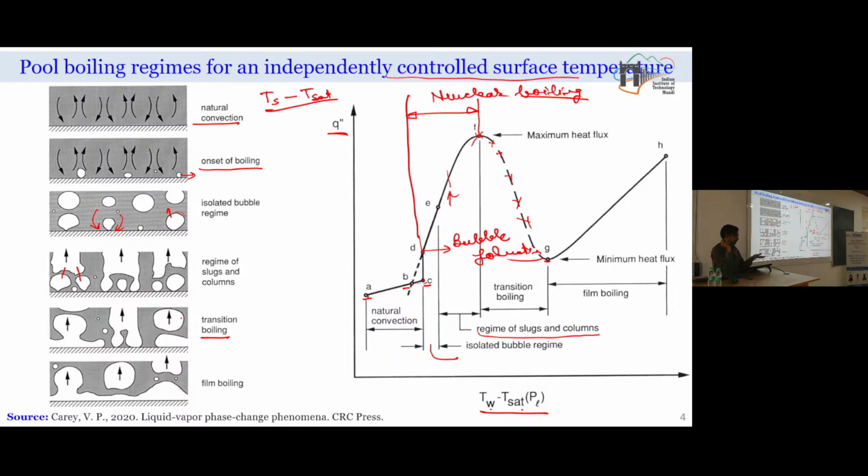of bubbles are forming, and once they leave the surface, they ultimately lead to a large portion of the heat transfer surface being covered with vapor, and vapor has low thermal conductivity in comparison to the liquid. So the heat carried by the overall fluid decreases significantly. After this point, the rise in temperature is significantly high, so in addition to the conduction and convection effects with the liquid, the radiation heat transfer effect also contributes significantly, and again we find a significant rise in heat transfer characteristics.